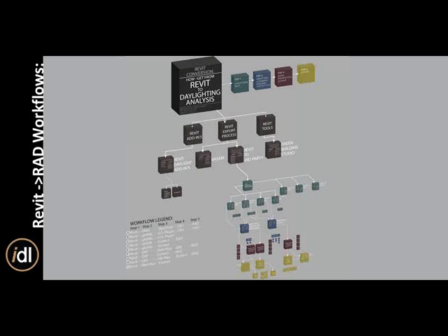Well, and again, it does export with the gbXML. Some thermal or material properties export, but not the reflectance, and it's not imported back in. So I guess theoretically, if you could get those to export, you could copy those properties and put them in the format of the materials file before going into Radiance. So I guess theoretically that would be possible if that's what they're talking about.